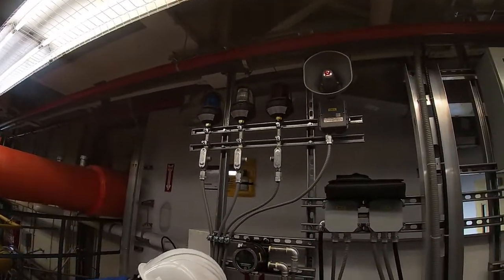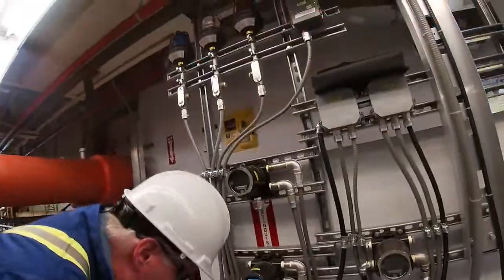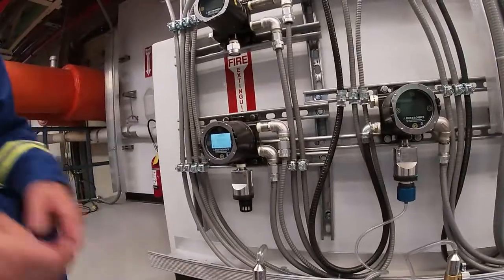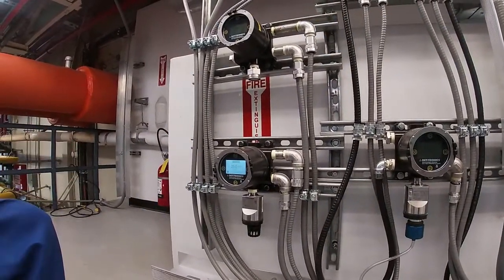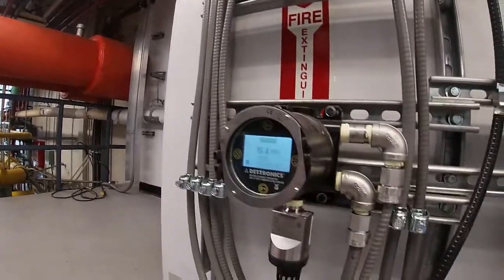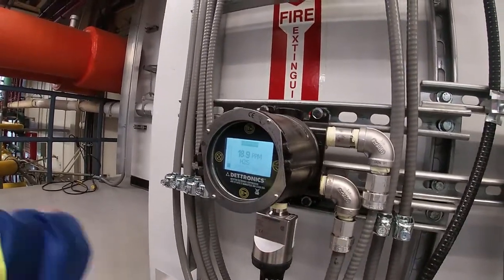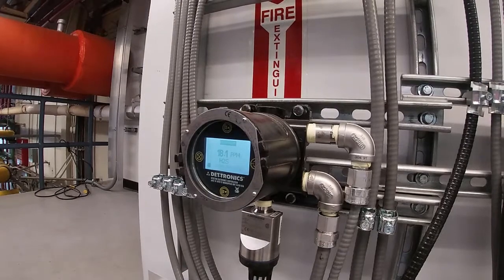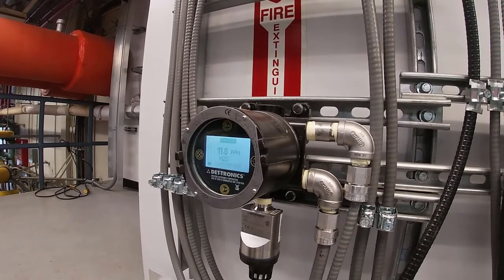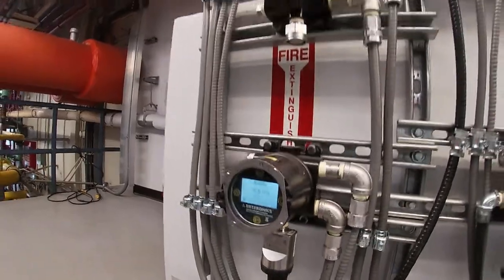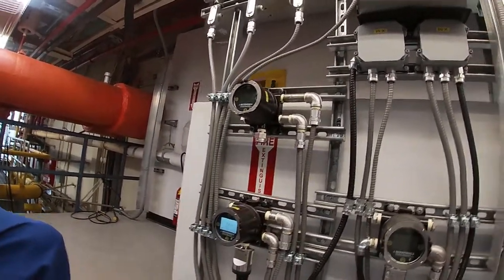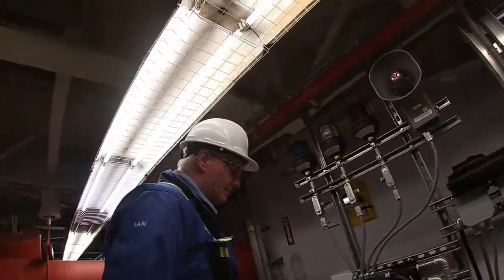So now I'll take the gas off. Again, it will have latched. So we're below our trip point now. We're in just our low alarm. There's a rotten egg smell in the air right now, a little bit. And I'm going to go down and reset.